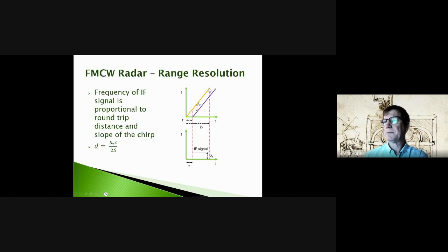And we transmit out a chirp, and that energy reflects off of objects out there in front of the antenna somewhere, and reflects back according to its radar cross section, which is a function of its geometry and the conductivity and other material parameters that might make an electromagnetic wave reflect.